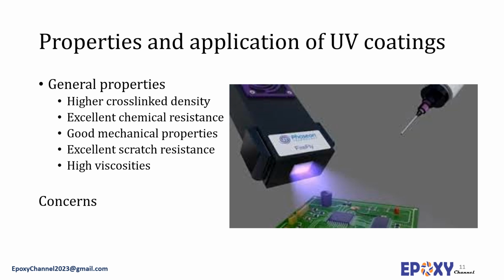On the other hand, the viscosity of UV paint is often not low enough for spray applications, and also as pigments often absorb UV light, the UV curing of pigmented systems is problematic. Moreover, the radiation does not reach all the parts of complex objects uniformly, resulting in an irregular cross-linking which adversely affects the film properties.